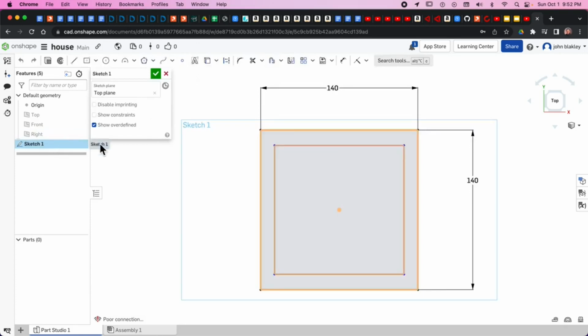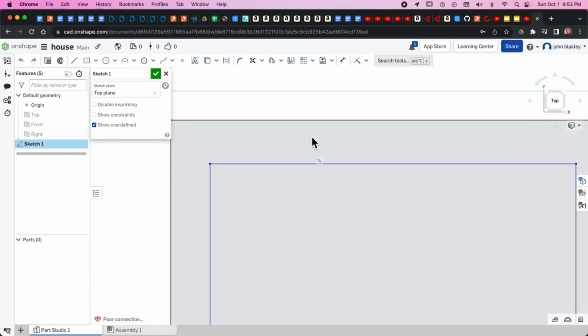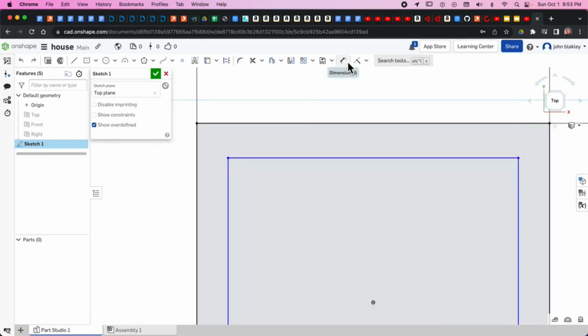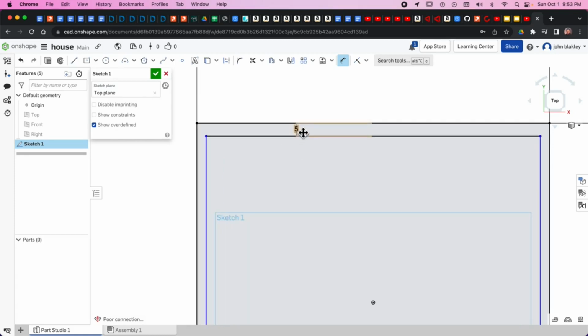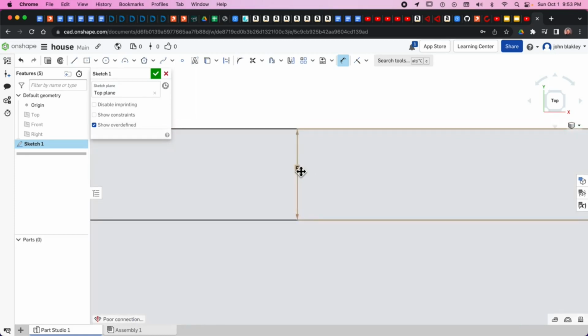Double click the sketch to go back inside it. All right, let's make the dimension from this line and that line a certain length. So dimension, click the line, but then look what happens when you click this line. When you hover, it turns orange. Click. Now it's saying you want the dimension from that line to that line to be something. It says 13. Let's just make it 5. Now if I zoom in, it's 5 millimeters.